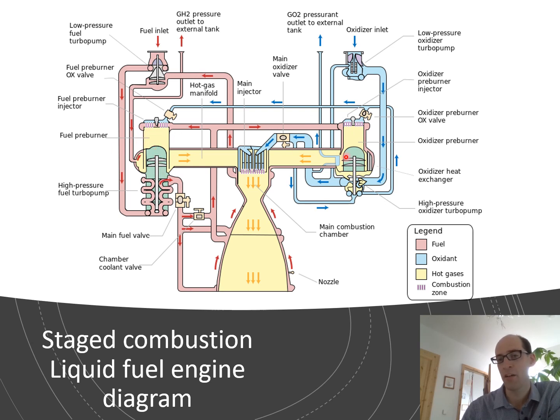So both these turbos run in a very fuel-rich manner. And there's a number of reasons for that, but one of them is that running it in an oxygen-rich manner would basically melt the pump. So they're run in a very fuel-rich manner, and what that means is that although the oxygen pump pumps the oxygen into the combustion chamber, the fuel pump doesn't. It pumps the fuel through the turbos, and then the exhaust from the turbo, which is very fuel-rich, goes into the combustion chamber, and that is where the ignition takes place, and the hot gases come out of the back of the engine.